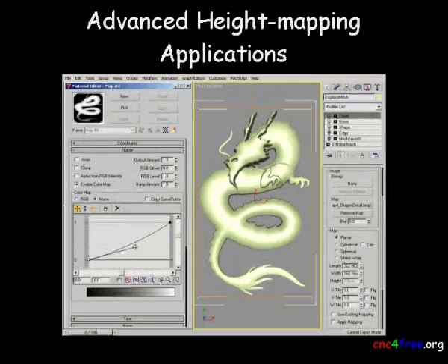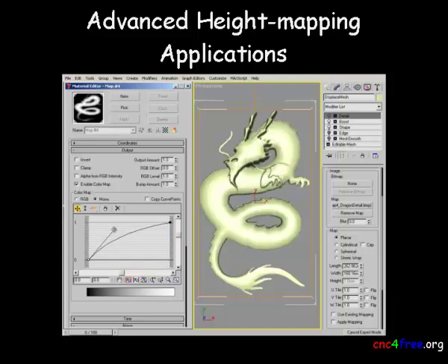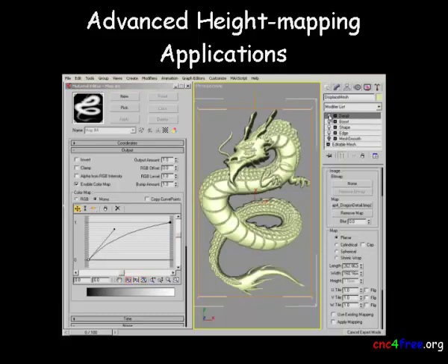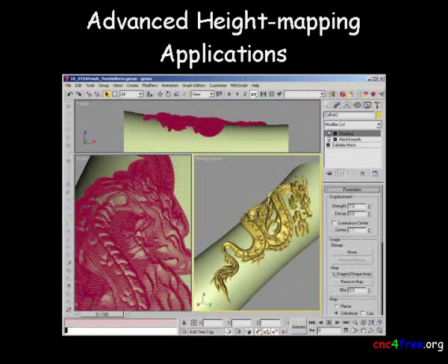While GMax is Windows platform only, those with particular interest in relief modeling or wishing to work using 4 or 5 axes will benefit greatly from its use. GMax offers more advanced exploitation of height maps. With live control over shaping, layered displacement, and use of non-planar non-uniform geometry, many more options are available. Functions and features operate equally well on vectors or splines to shape tool paths for 3, 4, and 5 axis cutting.